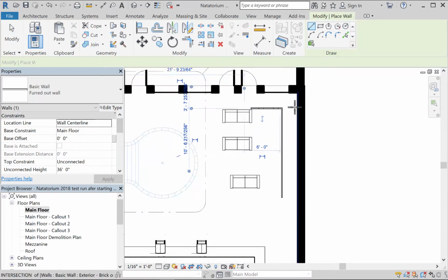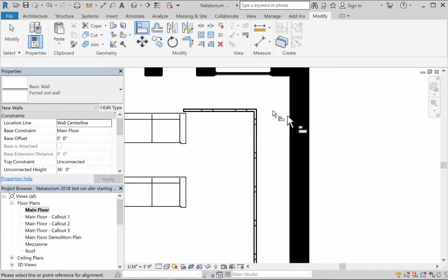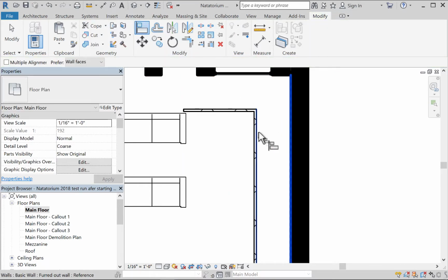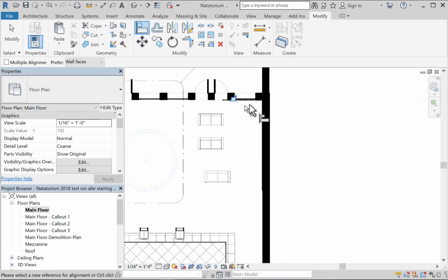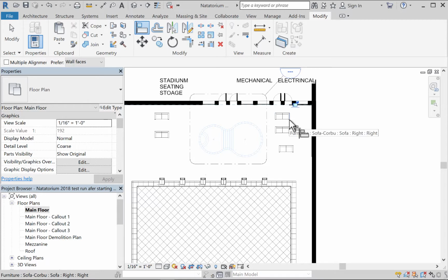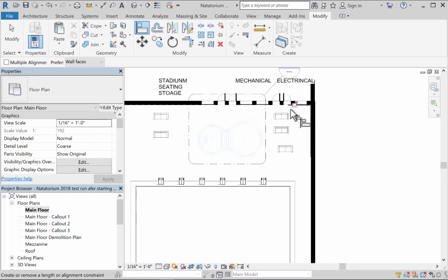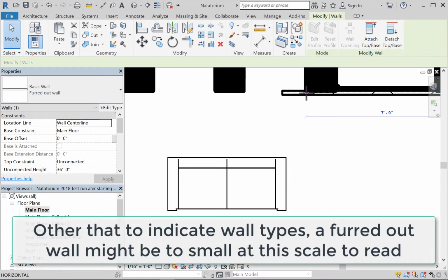This wall is going to be built right in front of your existing wall. Okay, it's a lot easier to draw them away from the wall and then use the align tool to align the faces of these things. They become a little tricky to move. What a lot of people will do is they'll just draw a line rather than actually draw a wall here, because at 1/16 inch scale, you basically aren't going to see these little devils. Also, you end up with a problem if you don't want this wall going in front of the door opening. So good luck selecting that little devil. It's really a pain.